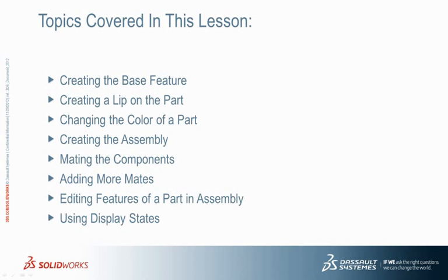In this video, you created a new part to use in an assembly. During the creation of this part, you learned about some new tools, such as offset entities and convert entities. You then used this part along with a part created earlier to create an assembly. You used the concept of mating to bring the two parts together to form this assembly. You also learned about editing a part and changing the display styles after it has become part of an assembly.